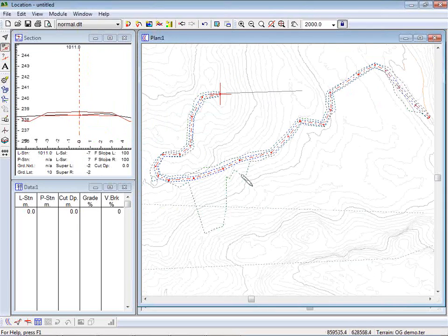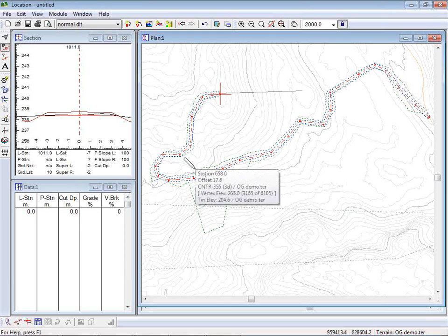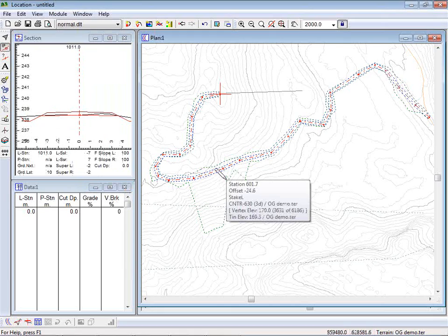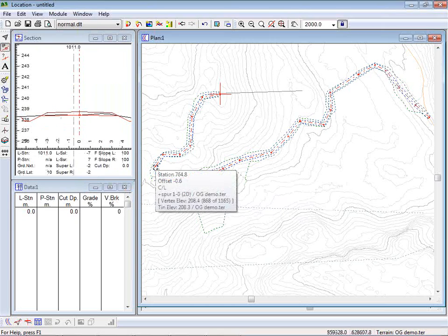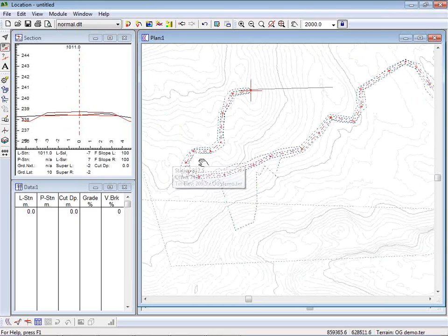Okay, so let's look at, first of all, I think I'm going to put in a couple of horizontal curves. There's really no correct order in this, so that's why I'm hesitating. I think I'll put the horizontal curves in first. You can do it after the fact too, but this is such a sharp corner. I want to make sure that it's a reasonable radius.